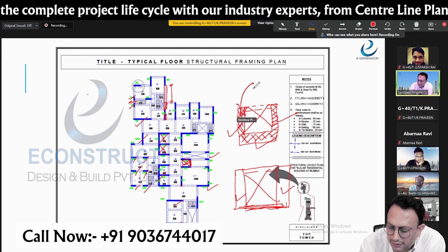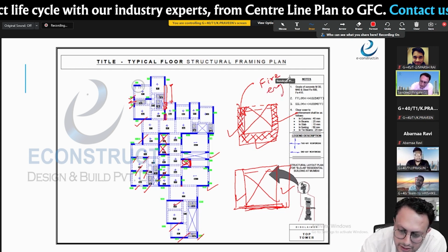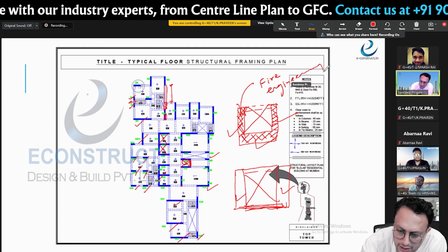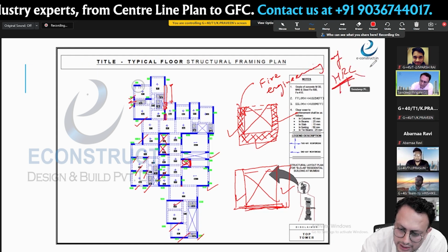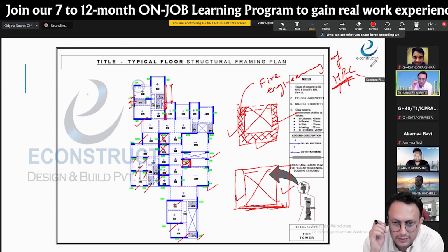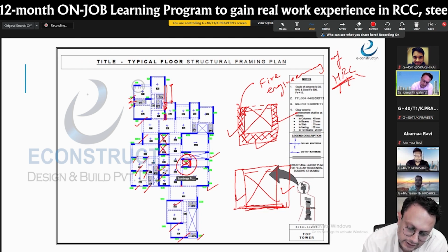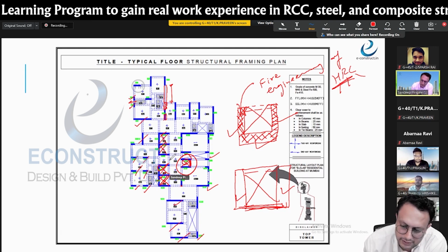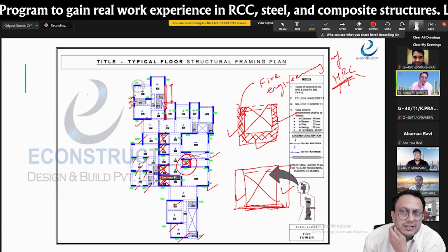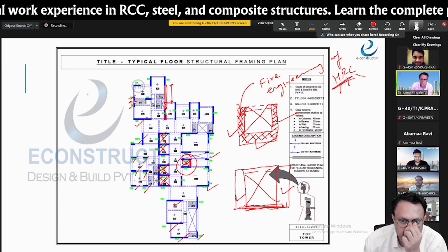Is this the requirement of the structural? No. This is the requirement of the fire engineering. Engineering of HRC. What is HRC? High Rise Committee. Okay, the shear wall is needed on all three sides. Specifically here. Here it is there already, so that is perfect. But here we need to give the cross mark. Correct? You cannot give the slab in the middle of the lift. Am I right? Yes.